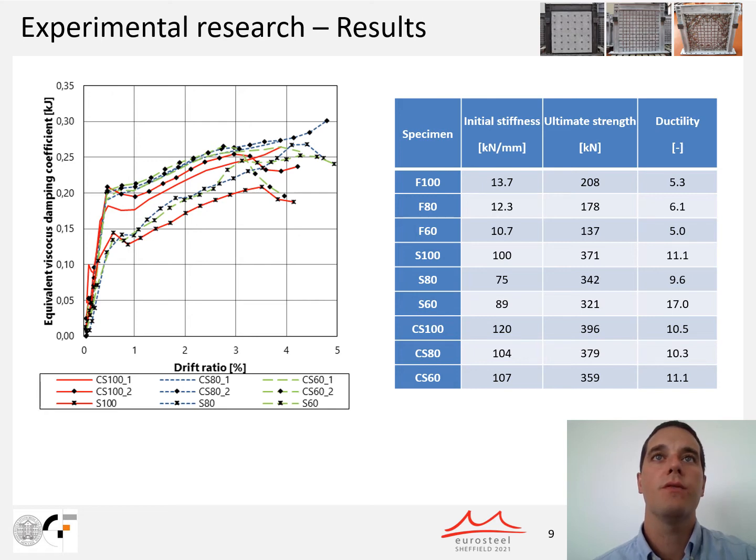Finally, it can be observed that addition of the reinforced concrete panel increases initial stiffness by approximately 25%, while the ultimate strength is increased by about 10%. If the mean value of the difference between ultimate strength of composite and pure frame specimens, as well as between steel plate and pure frame specimens, is calculated, values of 203 and 170 kN are obtained respectively. This leads to the conclusion that influence of the reinforced concrete panel on the ultimate strength increase is approximately 19%.